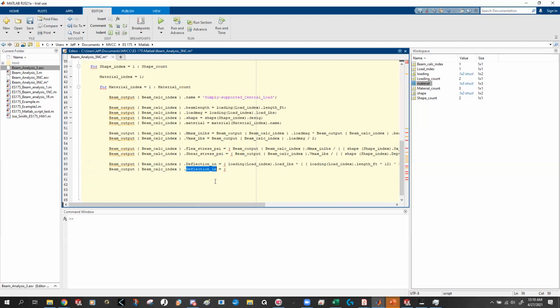So that can be a variety of things, but it's kind of like a quick factor of safety, if you will. But it's not an actual factor of safety. We'll talk, that's a different story, but it's just a basic rule of how close we are getting to where we don't want to be. So we'll call it yield ratio.